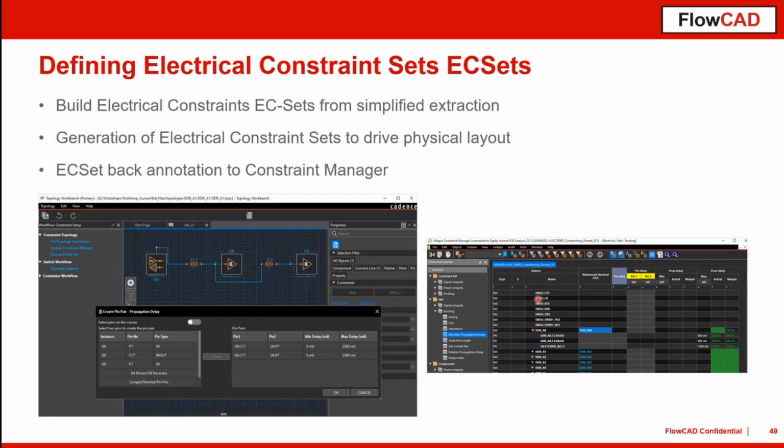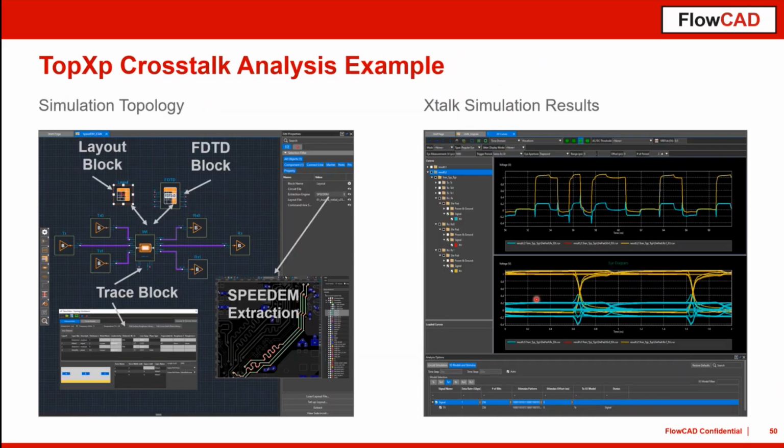As mentioned before, we have different ways to create such interconnect models. We can place different types of interconnect. In this case, I use this W element for the trace line model, which has been defined with this trace editor. But we can also change to some extraction engines. In this case, I've enabled Speed EM.